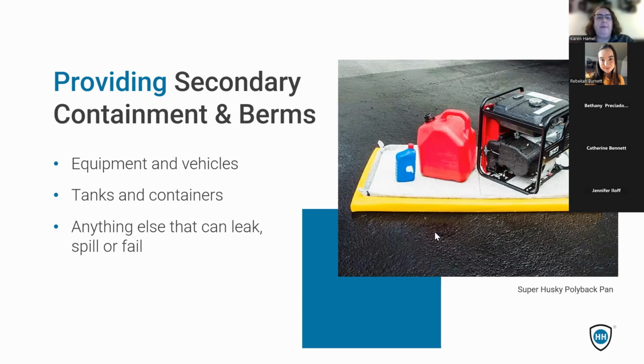And they actually ended up creating an area that had secondary containment so that all of the leaks and drips that were coming from those vehicles, the large trash trucks, were contained and retained, and they were able to separate the free oil before it went through their oil water separator and make it more efficient. So think of it not only for containers, but also for anything that may be in your fleet. Is there a way that you can contain an area and prevent oil, particulate, whatever else is coming off of that equipment, vehicle, or whatever it may be, from entering the environment?